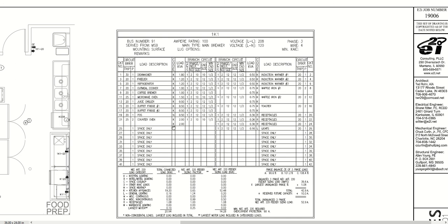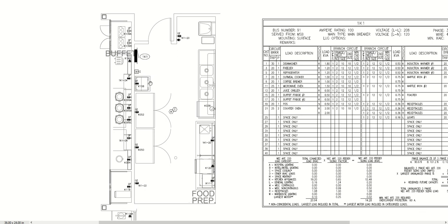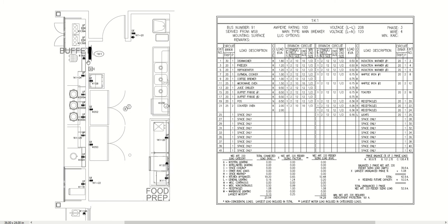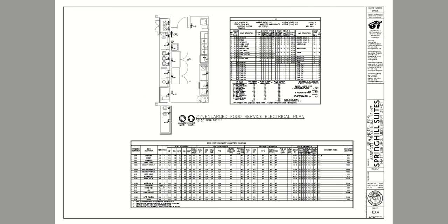So you can see there's quite a bit of kitchen equipment here. If you look down in the load summary, we do get to take that largest diversity factor, 0.65. The total load was a little over 19 kVA, but after we diversified, it's really a little over 12. That really helped, because you don't expect to run all these at the same time all the time. We do have a few other miscellaneous outlets on here, and there's the panel location here in the kitchen, and all the equipment connections. So it's a pretty typical small kitchen, with the equipment connection schedule and the panel itself.